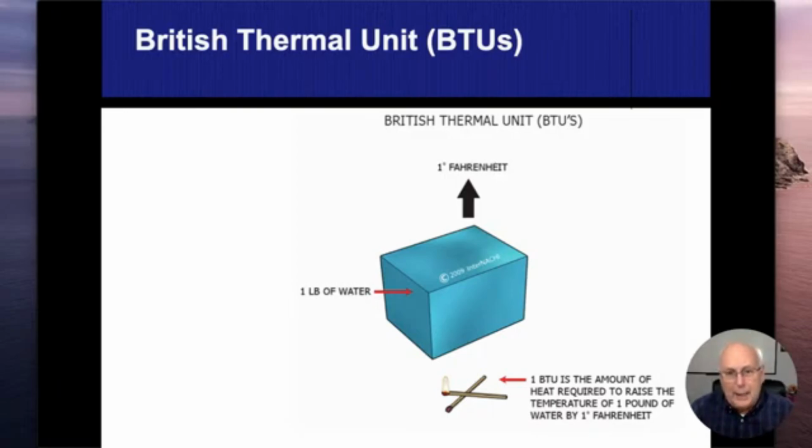But with natural gas, which most of the Chicagoland area here we have, we actually have the ability to measure how much gas gets used to create the fire. We can convert that amount of gas that's being used into BTUs. So on my website, thehomeinspectors.com, and then if you go under education and employment there, you're going to find a link to a gas timing chart on there.